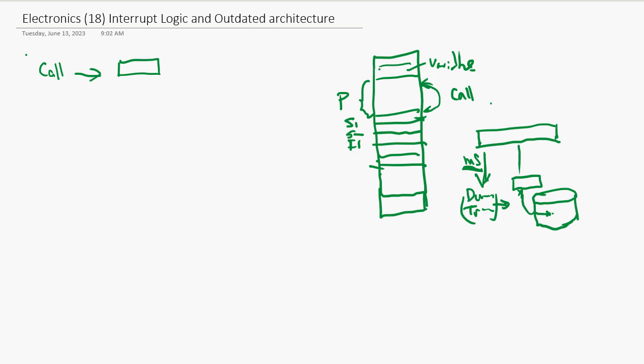Then it sends the interrupt signal, and this interrupt signal can be masked off or set a priority by the system. The OS does all the management. When an interrupt comes, whatever program is doing, it jumps to this interrupt.